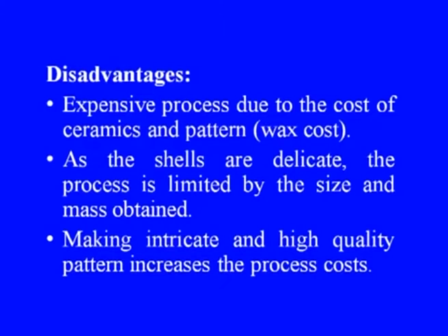Now, let us see a few disadvantages of the process as well. The process is expensive due to the cost of ceramics and the pattern, which is made of wax. As the shells are delicate, the process is limited by the size and mass obtained. Making intricate and high quality patterns increases the process cost.